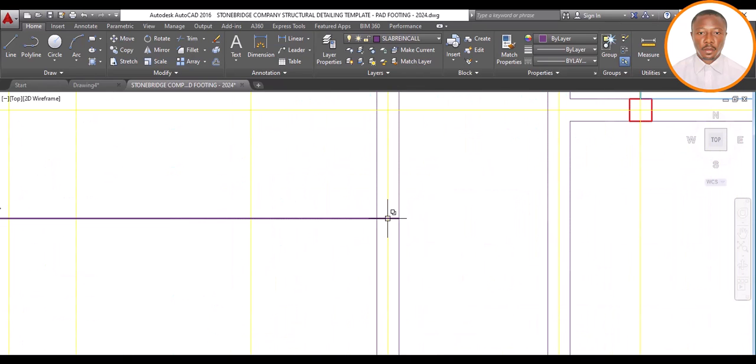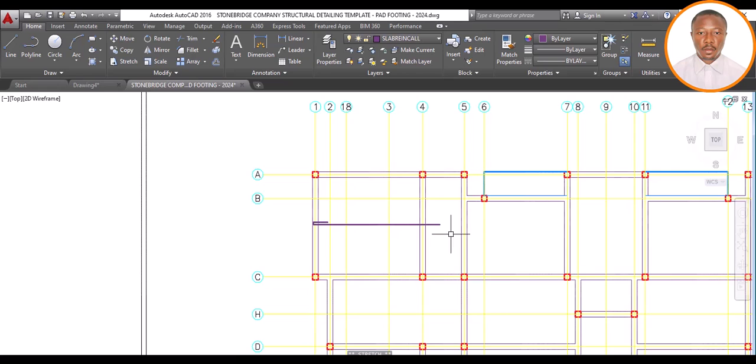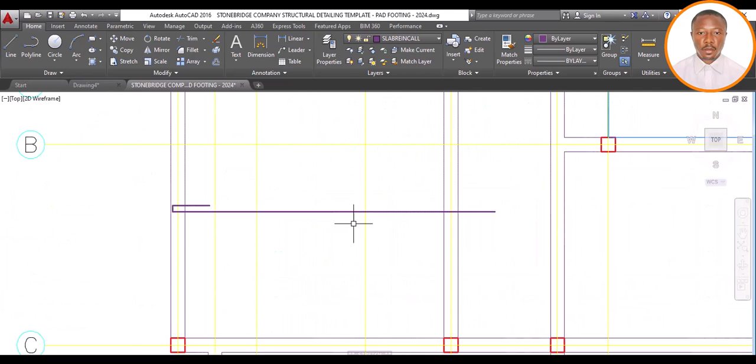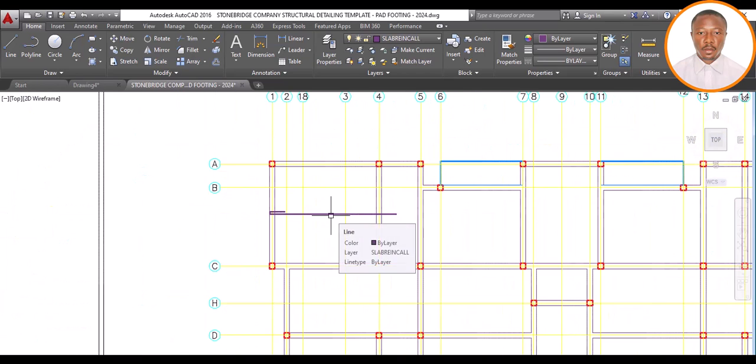Now I'm coming here. All I need to do, because definitely I will not stop here, is that my reinforcements have to enter the next slab by 600, which is my lapping. So I enter 600. So that is that. And coming to this other aspect again, I'm done with this slab for this x-axis. For this direction, I'm done with this slab.